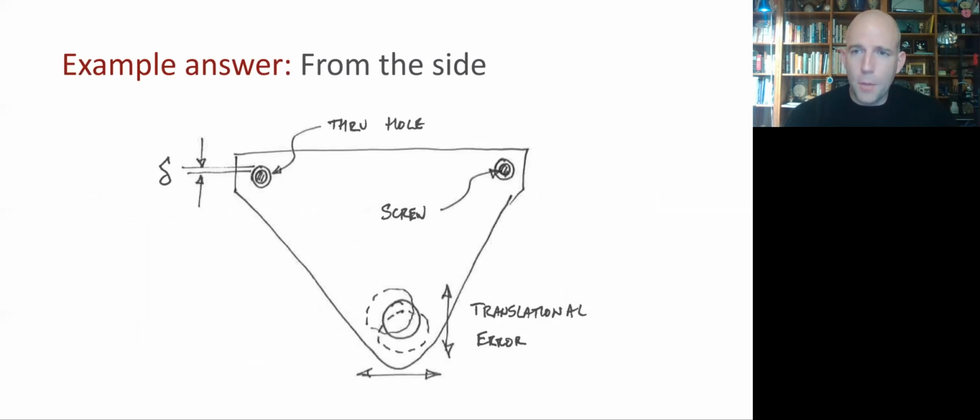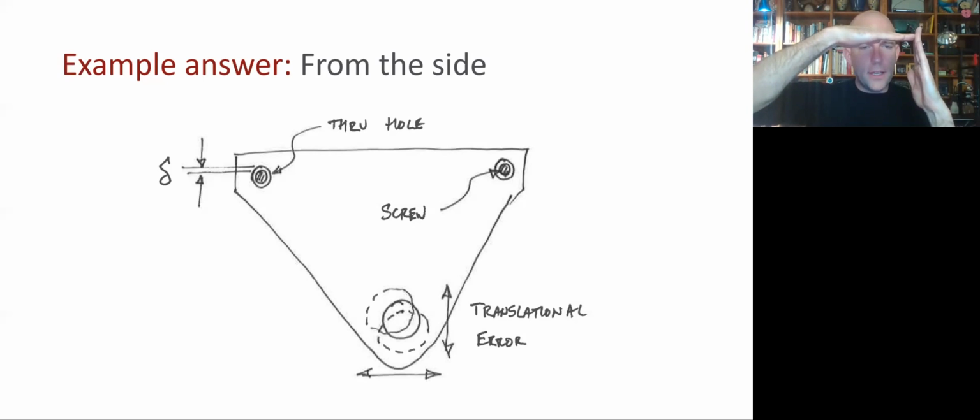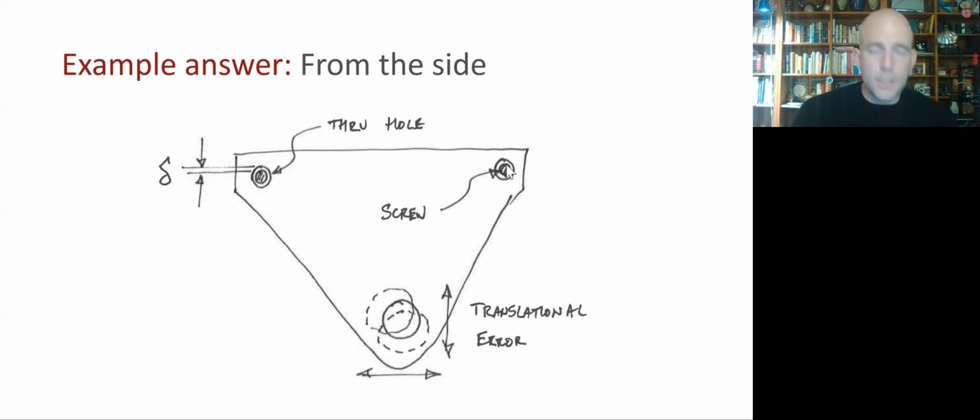So here's a common solution where we've taken this thing and broken it into 2 side plates and 1 horizontal plate. And then we're connecting the vertical plate to the horizontal plate with some through holes in the vertical plate and some screws that are, say, threaded into that horizontal plate. The strength of this design is that it's very simple. You have these planar shapes almost. Certainly the vertical elements are planar. So they could be manufactured, say, by laser cutting or something. The horizontal element will need some threaded holes, so that's a secondary manufacturing process. It adds a little complexity, but still fairly simple overall.